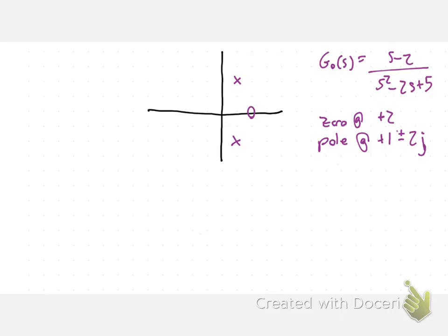Then, as we increase our k value or decrease our mu value, and let's go ahead and use a different color, we're going to have it become an underdamped second order system, and then move towards being an overdamped second order system. And so this one will match the other and then head out this way.